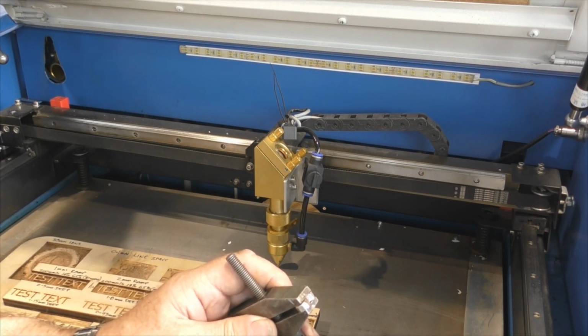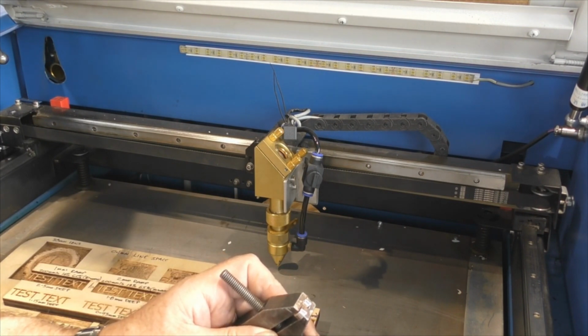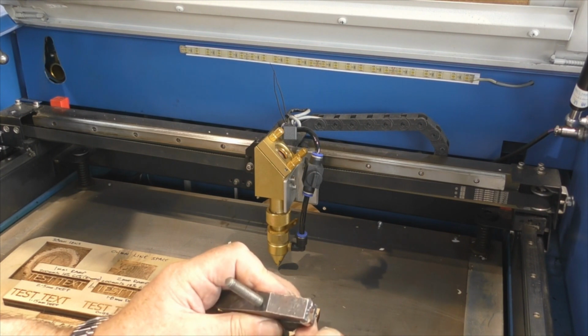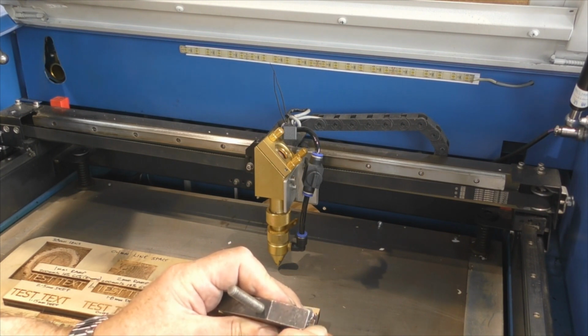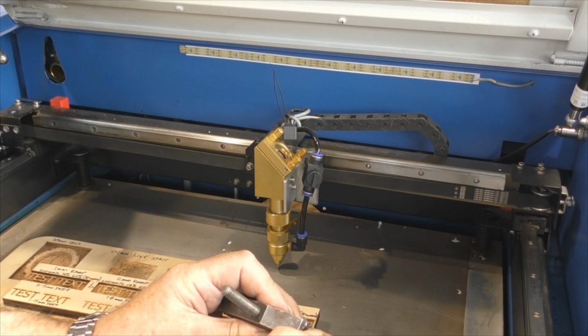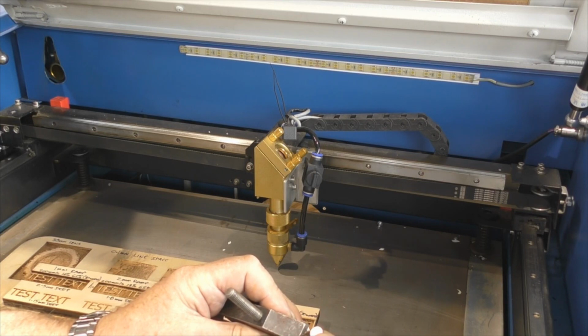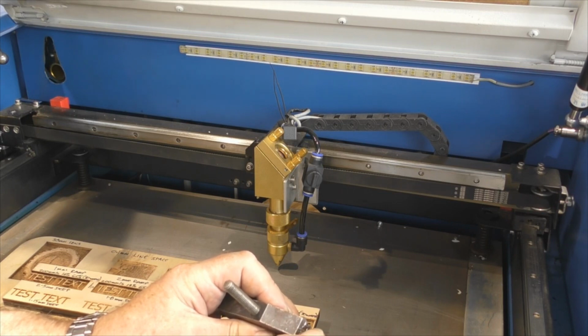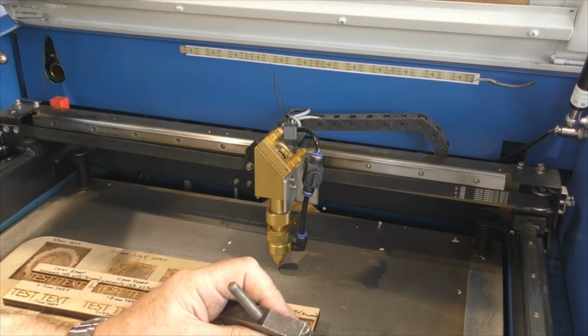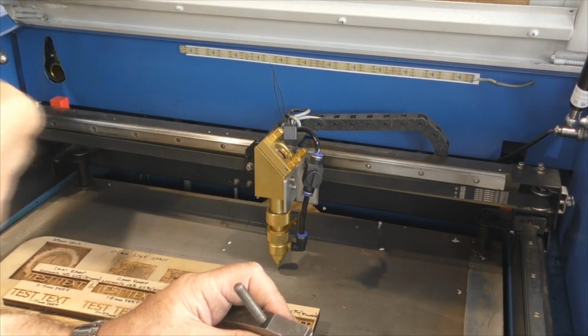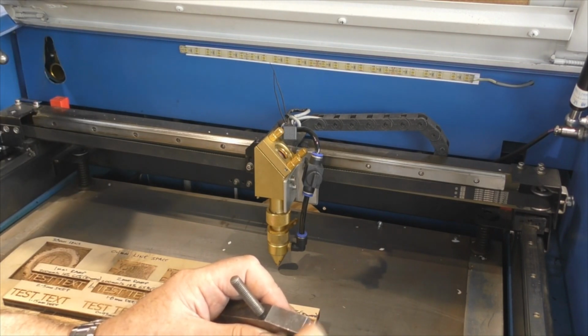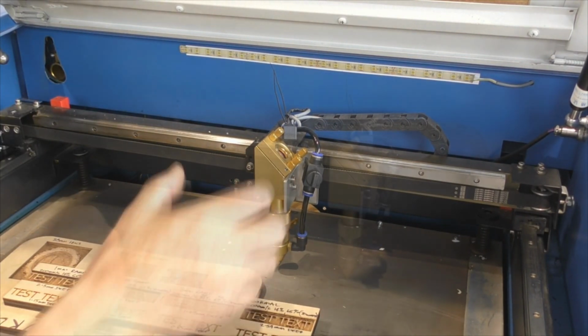They're not good neighbours, but I need them to be like that because basically a stepper motor is doing something like this. It's attracted to that pole there, and then it jumps across and leaves that one and sticks to that one instead. So it jumps in discrete intervals between poles inside the motor, and that's what you can hear, and you can feel that resistance as the poles are attracted to each other.